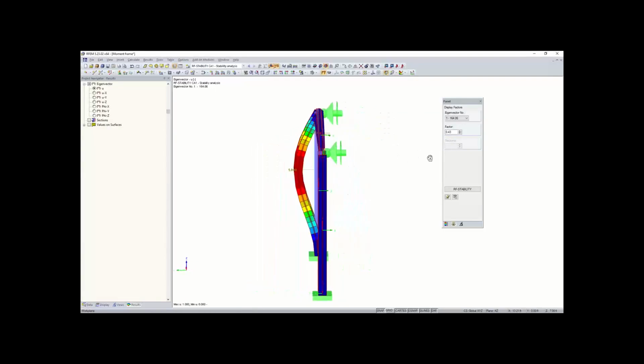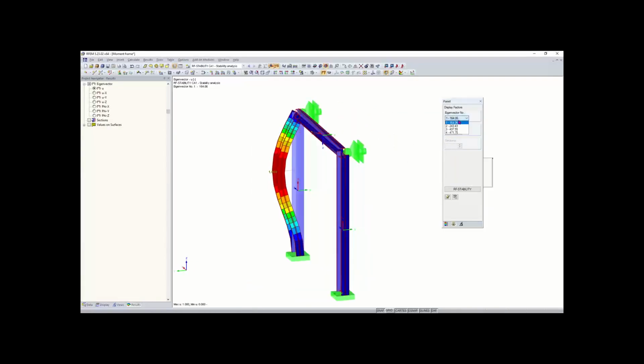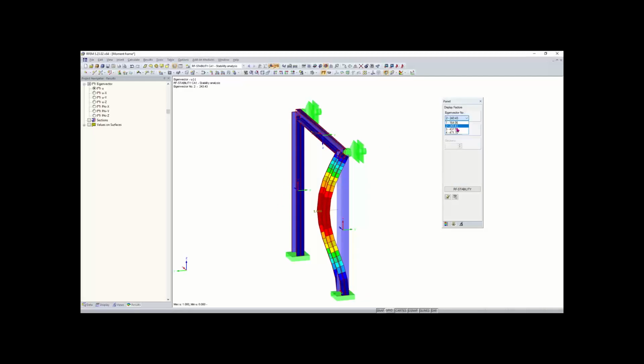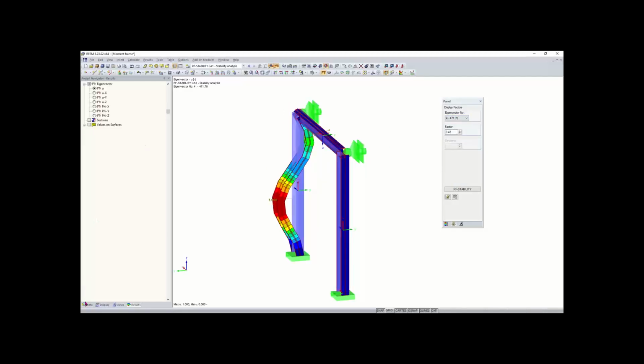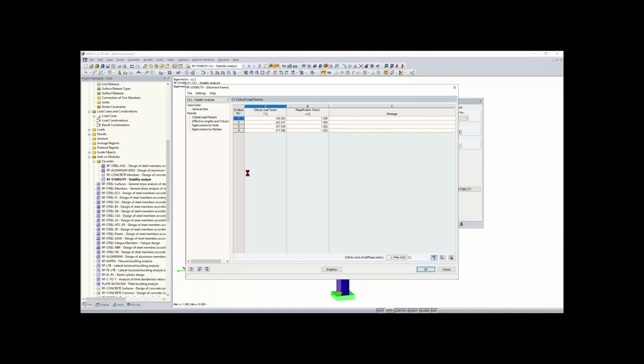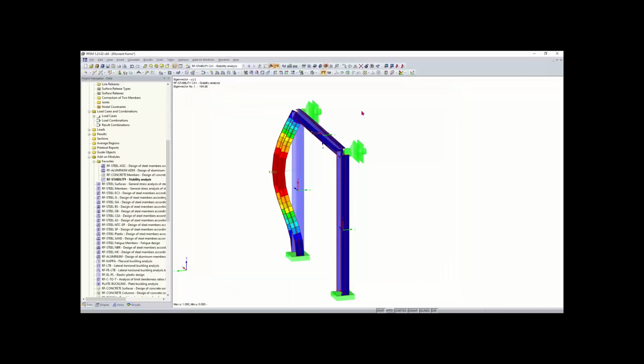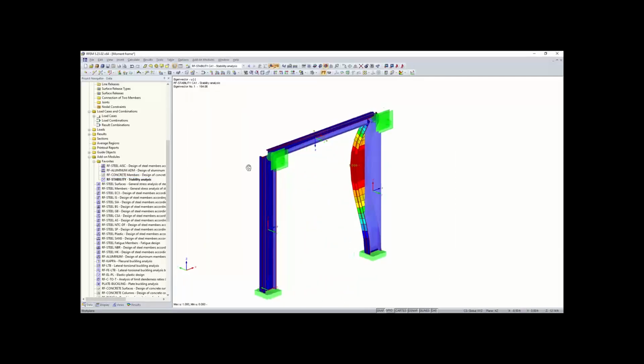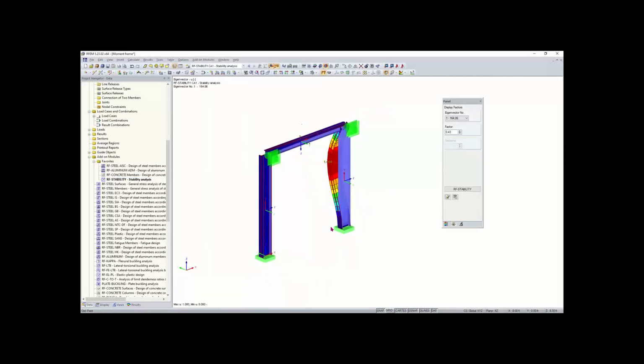supports we added here. You can see that we don't have any out of plane deformations at the top here. And also I'm sure our critical load factor has changed. It has increased from 20 to 164, so just adding those supports has helped a lot. And so that's the end of the calculations and modeling for our Euler case 1 example and for our moment frame.